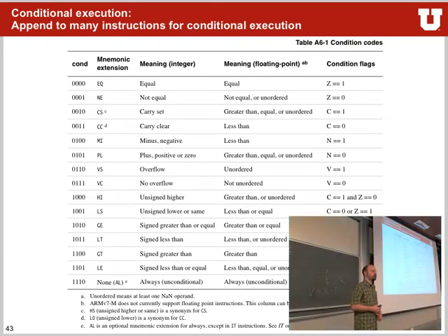Of course, we also have the branch instruction, so you can conditionally branch to a different function or somewhere in your memory. But sometimes it's only one or two functions that you actually want to have conditional, and that way you can use it in a far more efficient way. Yes? Do you just append it onto your instruction? Yep. So you say like ADD. Just add any. Not all of them have it, but most of them.